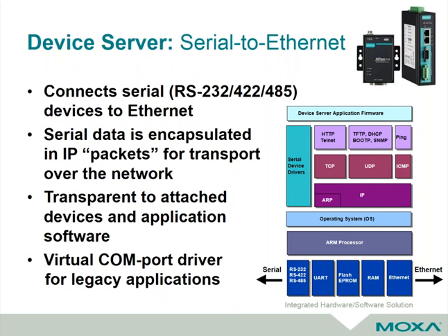You can see a couple examples of units up in the upper right-hand corner that can take an RS-232, 422, or 485 device and quickly get them on Ethernet to be able to grab that data. These are kind of interesting because they're a total plug-and-play device. In about 15 minutes, you can set one of these up. And these work on the concept of just basically taking that serial data, putting it into a UDP/IP or a TCP/IP packet, and helping you transport it across the network.